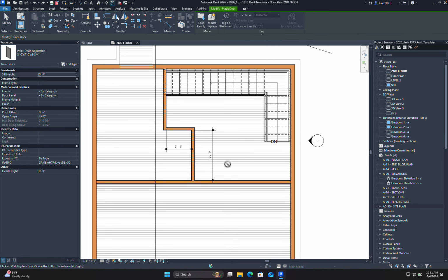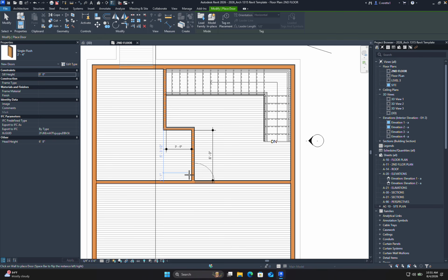I don't know, something about me just wants to put a door there. So let's, do you guys know the minimum door that we need for a bathroom? Non-ADA. This is where you really start to test your skills. 2 feet. You only need a 2-foot door in a residential area. Now, if somebody is an ADA requirement, do you know the width of the door?